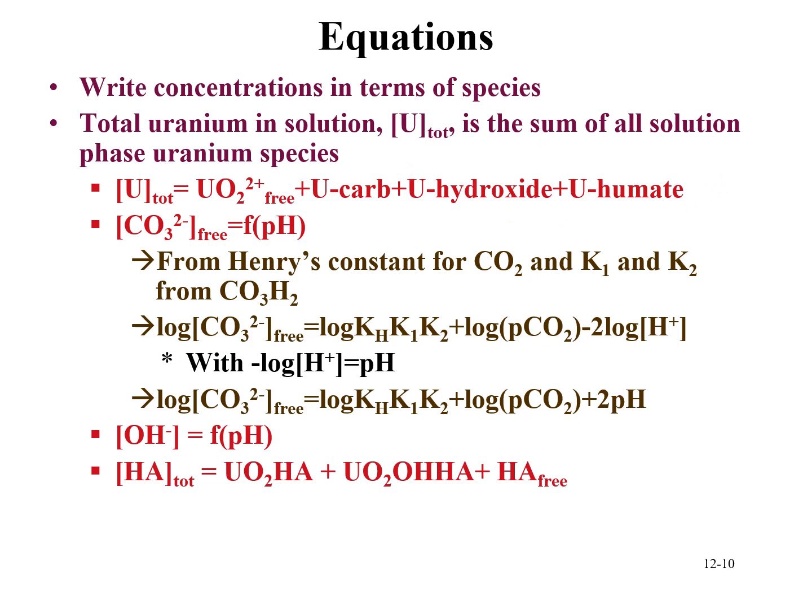Since carbonate is a function of the speciation, we also need to know something about the carbonate concentration. We can actually get the carbonate concentration as a function of pH. If we utilize Henry's constant for CO2, in other words, if I know how much CO2 is in the gas phase, Henry's constant will tell me how much goes into the aqueous phase. That will form carbonic acid.